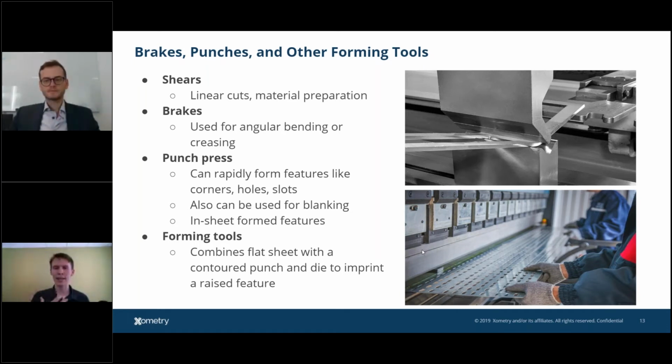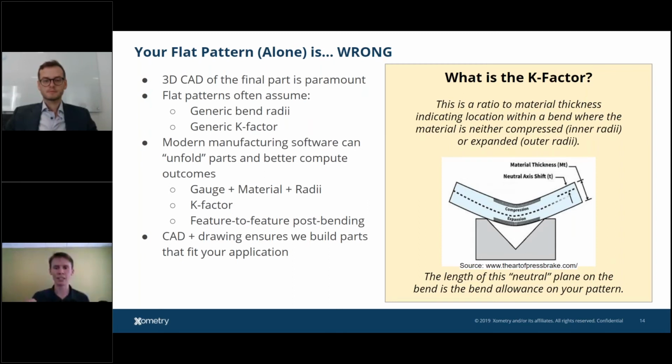And actually, I should have put a note on here, but one of the most common things I see on the DFM side is seeing both the inner and outer dimension on a drawing for the inside wall and the outside wall, and ultimately best practice for sheet metal is choose one. Just because you're dealing with a gauge of metal anyway, so one of those dimensions is moved, and by having both, you're actually not indicating what's the most important thing to you on that project.